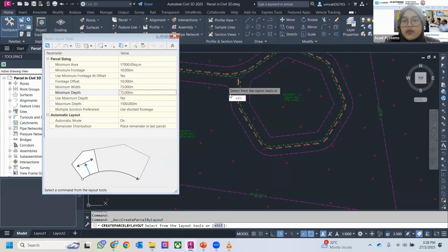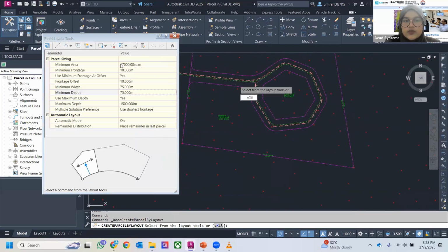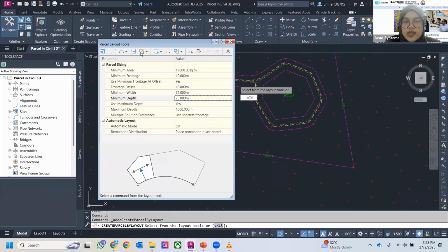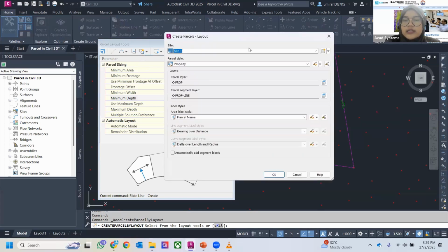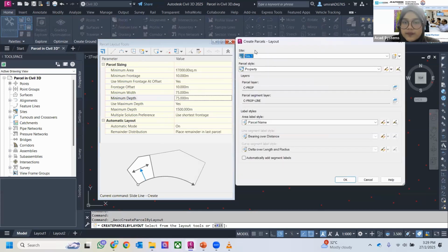All right. And then how do we create a subdivision? To do that, you just go to this tools here, and the create parcel from sideline tool will show here. If you didn't find that one, you just click on this drop down. There are a few more tools that you can use to create this subdivision. Other than that, you can use swing line or freeform. Freeform means you just sketch wherever the subdivision you want in your parcel. I'm going to use this select line because it will use the data that I just inserted.